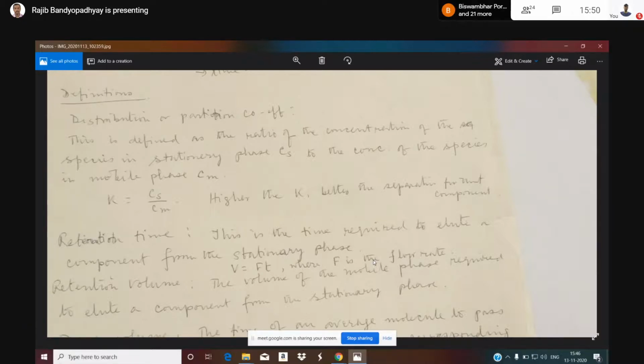They know what type of temperature gradient should be there. Usually it is not kept constant, because then the separation will not be very good. Since the gas chromatograph is used for separating the components, we must ensure that at the exit all the components are separated. If they're mixed, there is no point in using the gas chromatograph. So we have to maintain the temperature and the gradient accordingly.